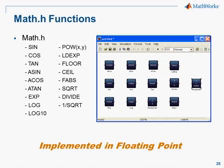Traditionally, CORDIC implementations have been used for such operations, but the logic for this choice is based on the outdated ASIC idea that logic is very cheap and multipliers relatively expensive. For floating point operations on an FPGA, multiplications are now cheap and have the advantages of predictable performance, low power, and low latency. Contrary to accepted wisdom, the multi-stage CORDIC approach is a highly inefficient method to build these functions.